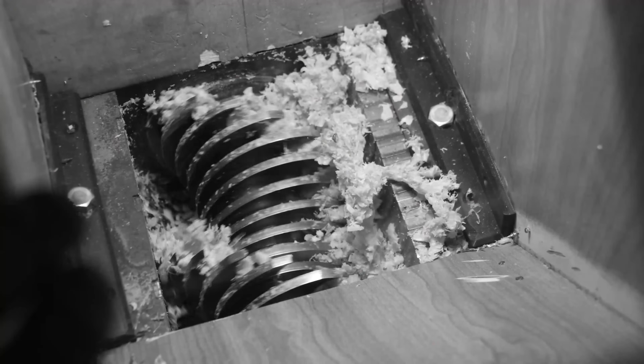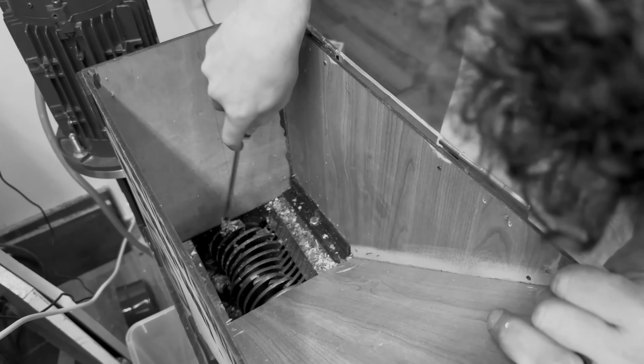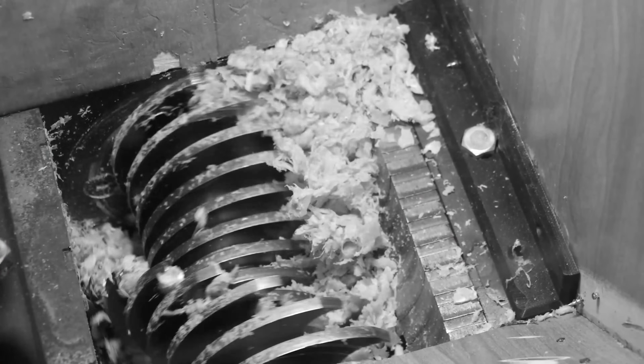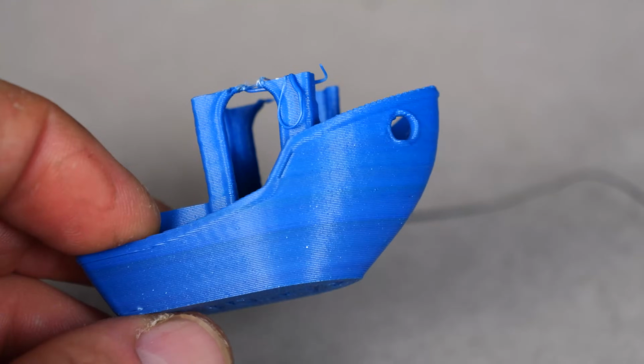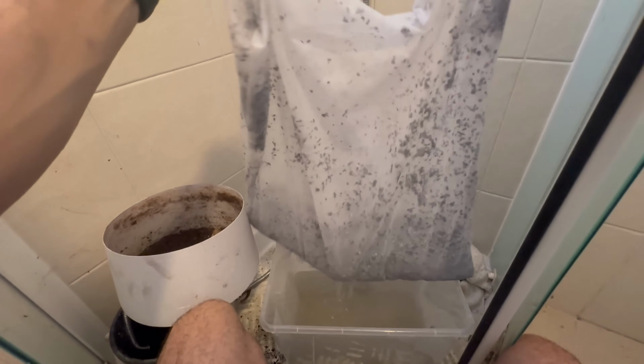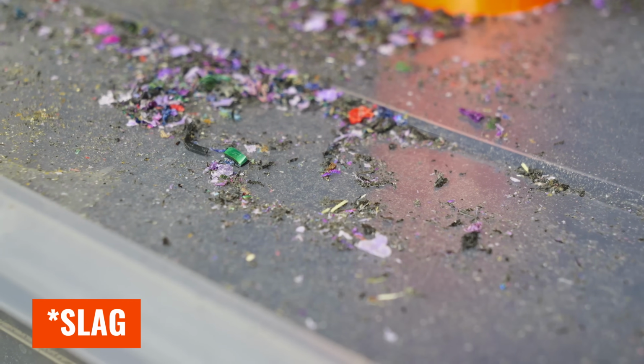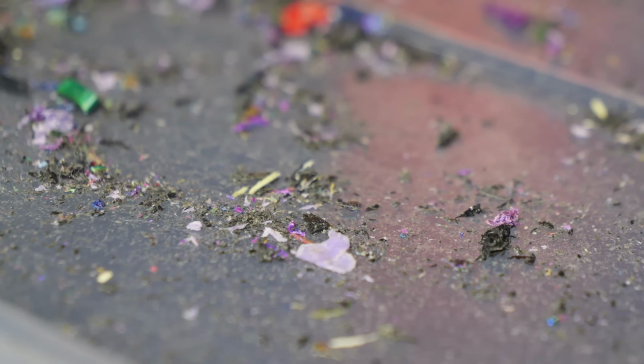Up next, let's switch gears, no pun intended, and talk about my 3D print recycling ongoing nightmare of a project. As you might recall, if you saw the latest installment in this series, I've been really struggling with clogs on my recycled filament, and no amount of washing or tossing it around with a magnet seems to be enough. So over time, I've come to realize that a big part of my problem comes not from contamination in the old 3D prints, but actually from small pieces of wood chips and welding flux that are falling off of the design when the motor exerts incredible forces on the shredder.